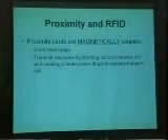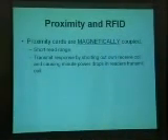Basically, when it's transmitting the data back, what it actually does is short its own coil. It's got a tiny capacitor in there to kind of keep it alive. It shorts its own coil out, which is effectively killing its own power source, but it causes a tiny volts drop in the coil that's actually powering it in the reader. And that's how it signals back, through this magnetic coupling.